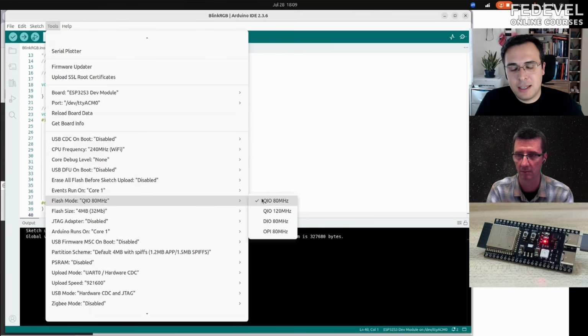And because the ESP32 runs the program from the flash address, it doesn't load the data to the RAM, and it doesn't run it from the RAM. It runs it directly from the flash memory. So it is quite important that the flash frequency, read and write, should be quite high, especially the read time, because the CPU shouldn't be stuck before it is loading the data.